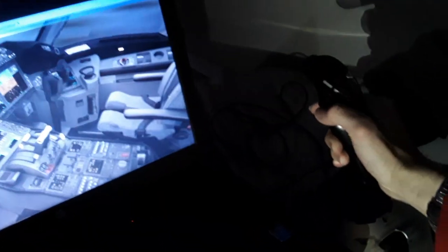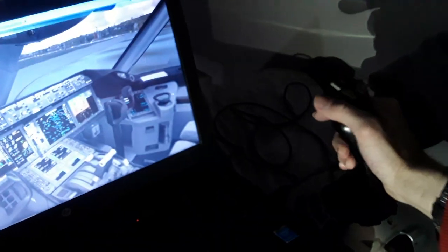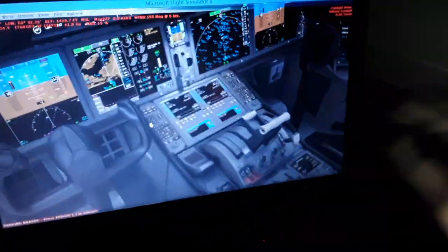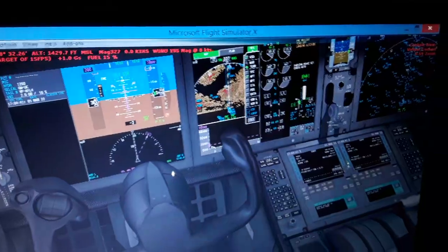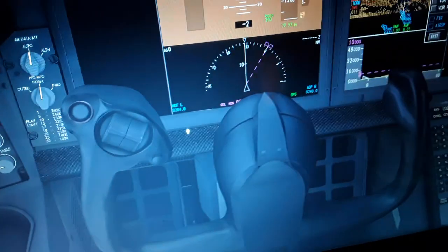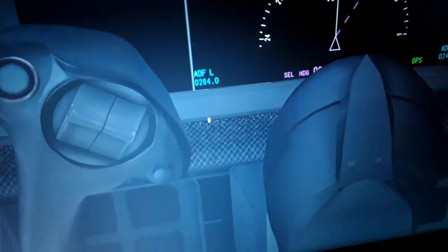In the Airbus we have the side stick priority, you can take either side or have dual input. You have the autopilot disengage also, side stick priority and the push to talk over here. Also in the Airbus we have the rudder pedals interconnected, moving together in flight. So I'm going to show you now the rest of the systems. I'm going to show you also the horizontal trim stabilizer here very quickly. This is the horizontal tail elevator trim, up and down. Over here move the elevator up and move the elevator down, so you see the horizontal tail over here.